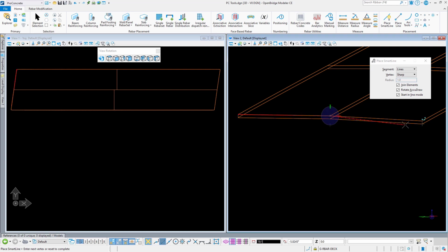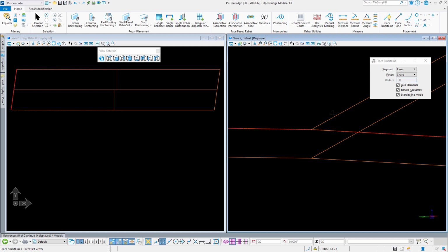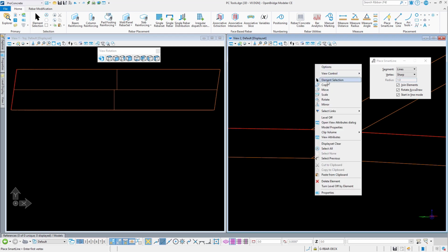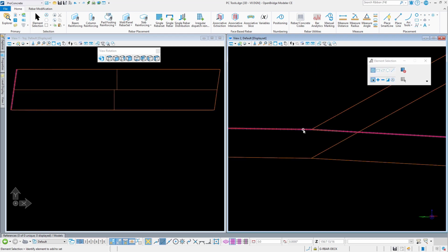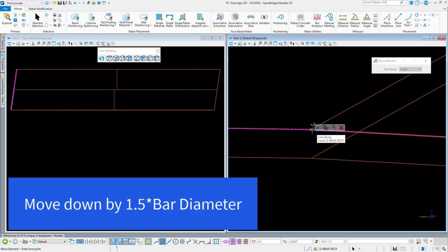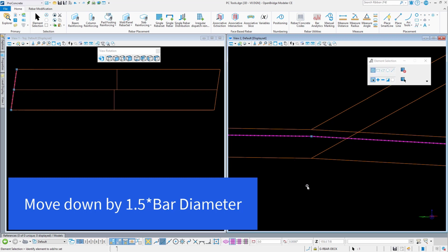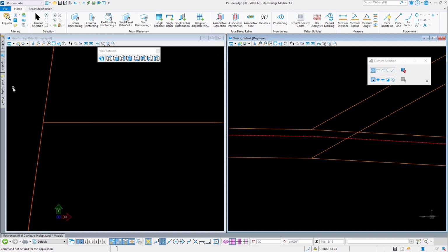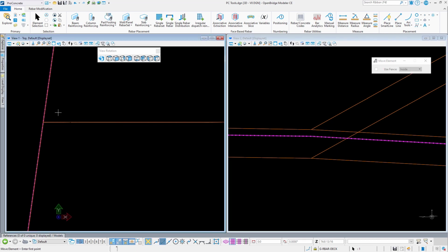So a lot of the times you're going to end up using a tool called irregular dispatch to model this reinforcement. And with the irregular dispatch tool, essentially we're going to need 2 or more 3D lines to help us tell the software precisely where the reinforcement begins and ends, and also potentially passes through. Think of this as a line representing where the center line of all these bars are going to be located, and we'll see that here in a moment.